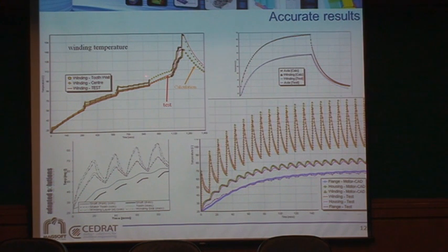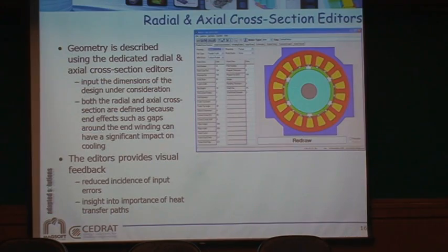And we can see in yellow the computation from motor-CAD, and in red, whatever was measured. So now we have to be careful, because when we talk about measuring the temperature of a machine, you need to know where you're going to take the temperature, because of course it's going to affect very much the result of the measurement. And then you need to look in a critical way when you look at both of those. So, other validation here, we'll see after what they are.